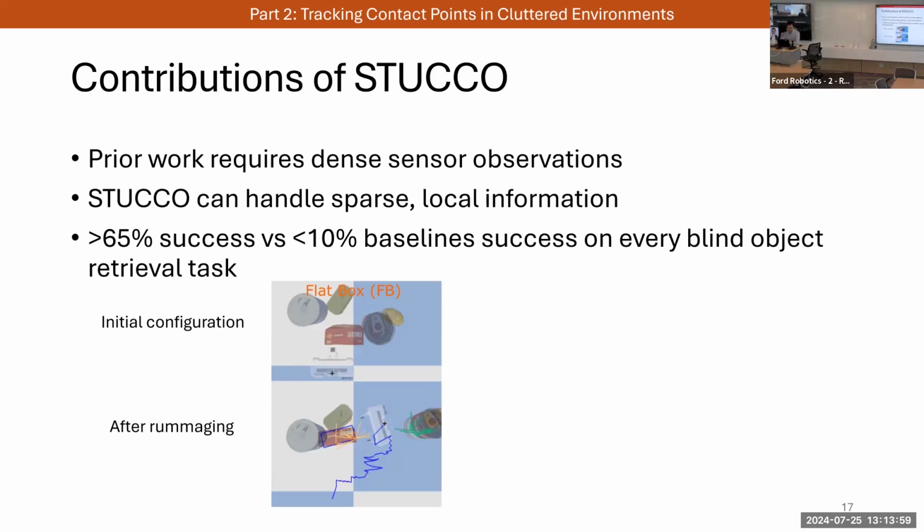So what the robot can estimate is the applied external wrench. And we are assuming that each contact is only occurring at one contact point. That's why it is sparse. I see. And you get a wrench at each of those points? No, we get an applied wrench at the end effector wrist. And then through a contact particle filter, we can estimate on the surface of the robot end effector where that contact was likely made. Okay, good, thanks.